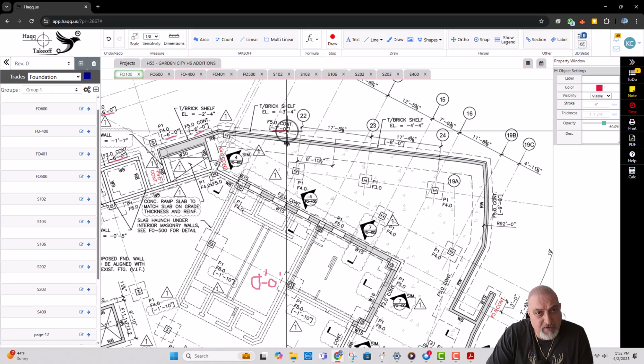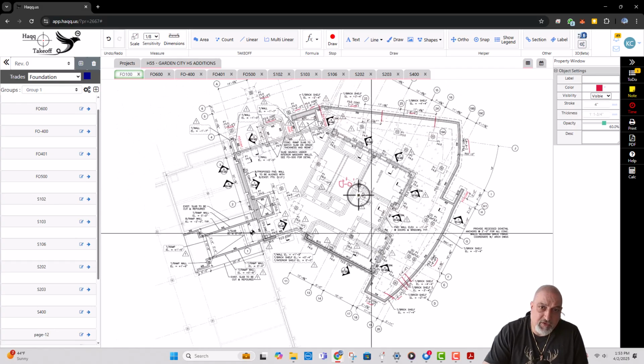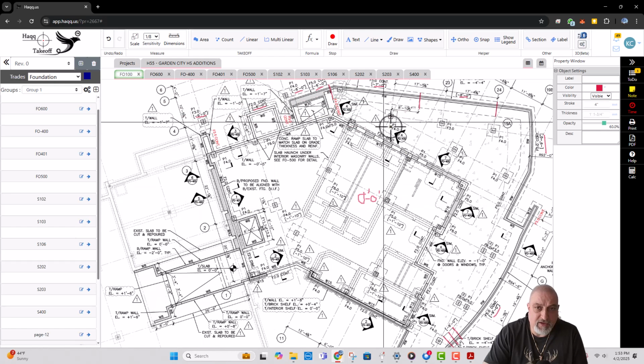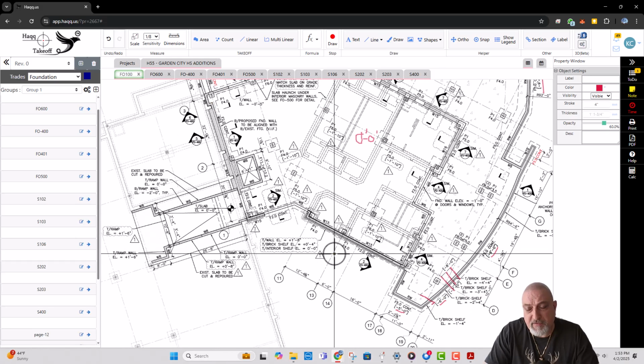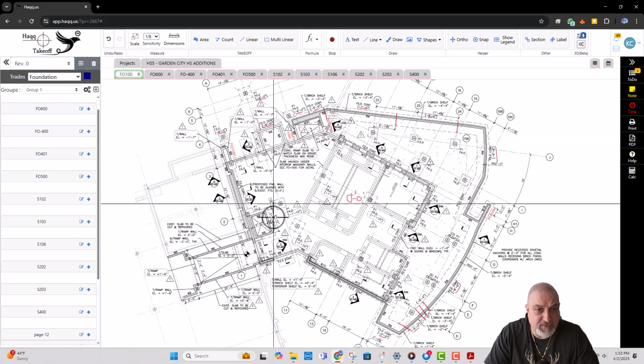Okay, when you come here, you got minus 7 here, so we can just step it up here. So minus 6 to minus 7, we're going deeper now. Now minus 8, we got another step here, and minus 9 here, so this is gotta be the step. Okay, so we understood what's going on here, but we don't know what the elevations here and back there. So let's take a look at the sections. Maybe they help us. If they don't, we need to find out what's the grade elevations and go down 4 feet below that grade elevation. But let's first look at these sections.